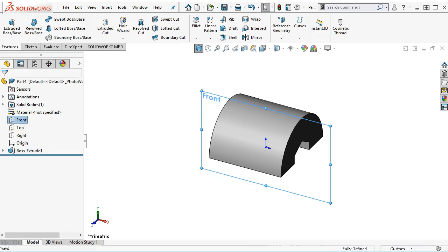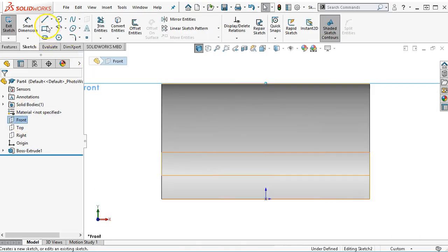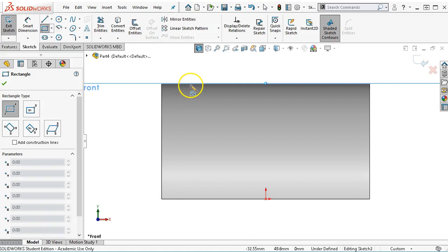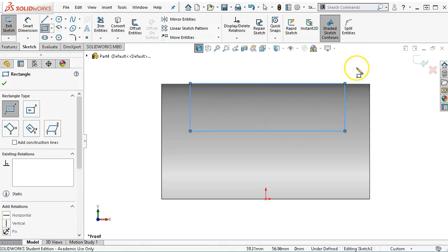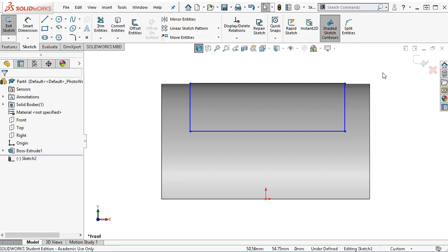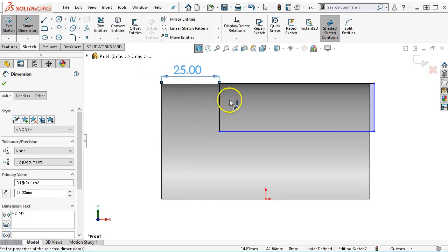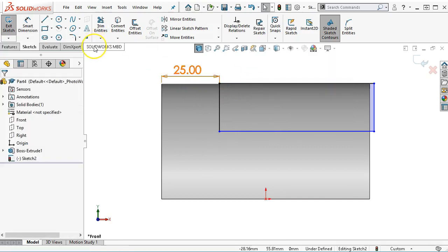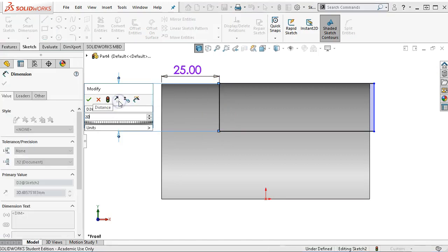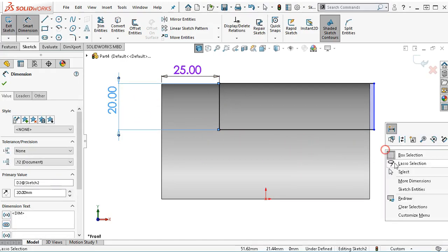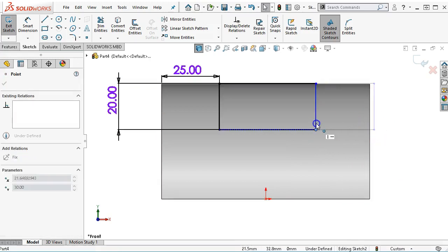Now I'm opening up a sketch on the front plane, and we're looking for that silhouette edge again. So as I drag along, well, in this case it's finding coincident. Okay, so we're in the command for the rectangle. And we have 25 on both ends as our dimension. And if I were to, let's stay in dimension one more and put in the depth of 20. So I could add the 25 on the other side.